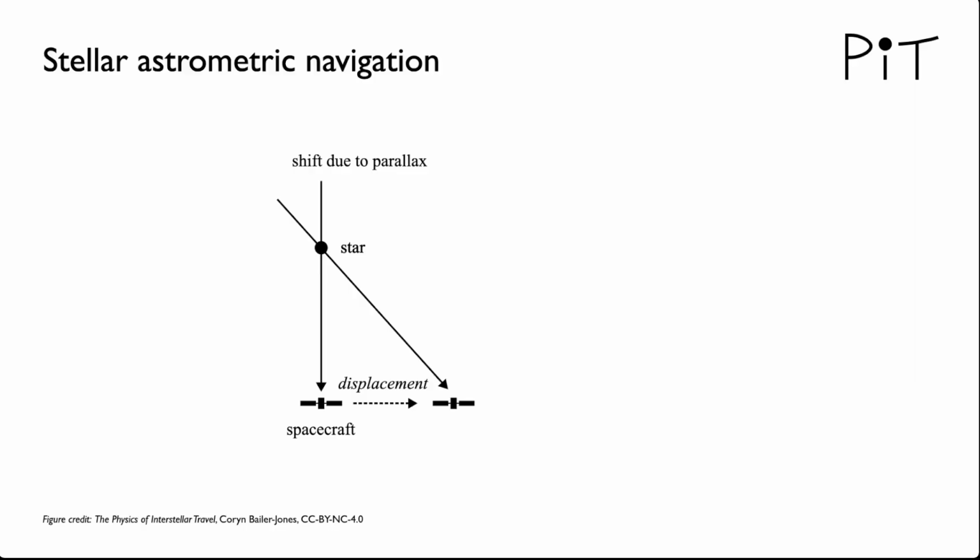To do this, we do not need to measure the 3-dimensional positions of the stars from the spacecraft, which would be very hard. We don't even need to measure their 2-dimensional angular positions. It is sufficient just to measure the angular distances between pairs of stars, a 1-dimensional measurement.